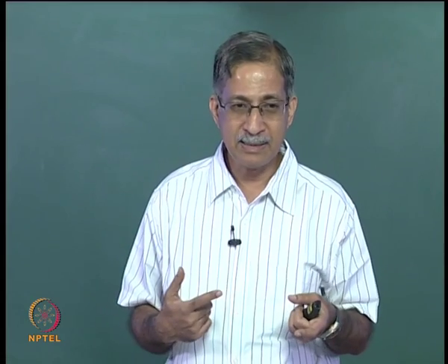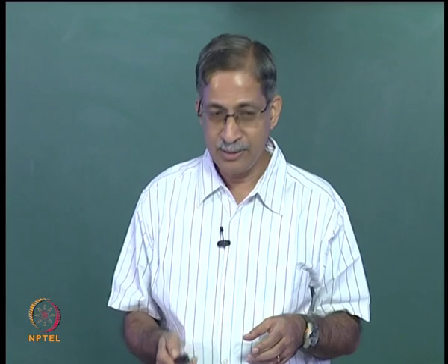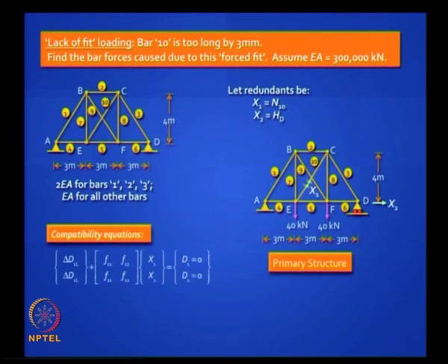What is delta d2L? Delta d2L is 0, right? Now this 3 mm you should write in a consistent unit, so it is 0.003 meters, and if it is too long you should visualize this as an overlap of those two bars by 3 mm. Is it clear? So that is all you have to do.